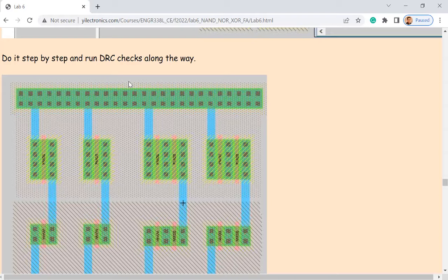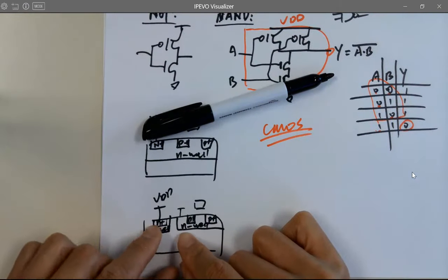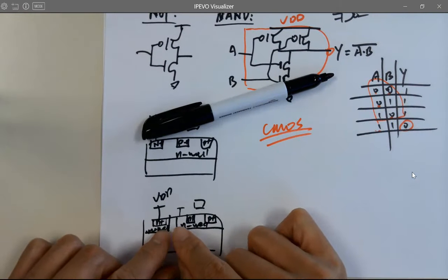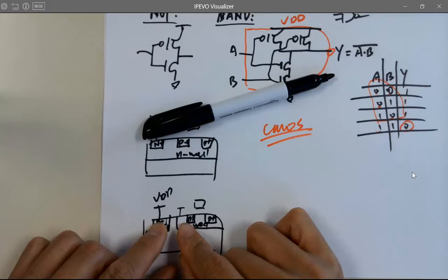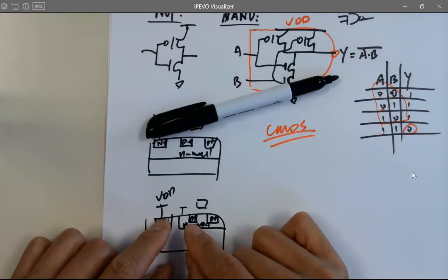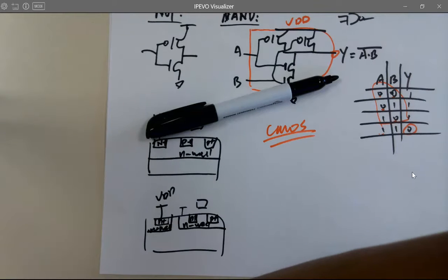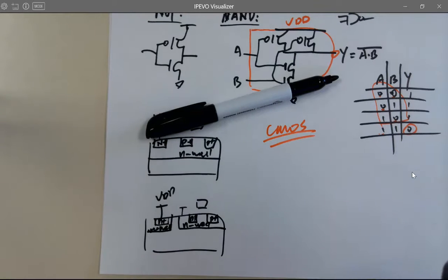The well check is checking if you have the good well contacts, or if you put everything in the same well. Or if you have for example, these two, right? If you pull this up, and there will be a gap, right? But by the design rules for C5, I think the distance between these two wells must be larger than something. However, if you do not overlap these two and have a very small gap, you have to zoom in 10 times in order to see the gap, which means the gap is tiny. But the process size, for example, is 500 nanometer technology.